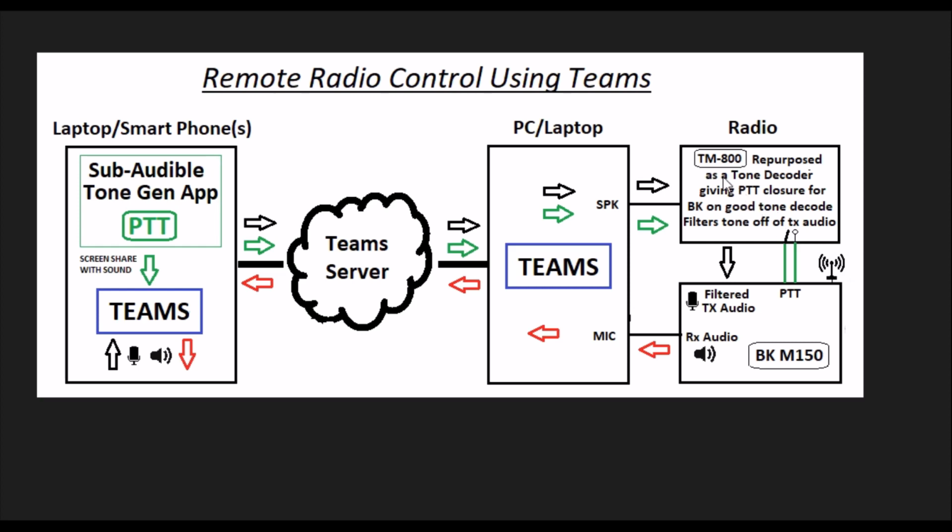But it works well. You do have to get the levels right, and all the other standard Teams settings that I talked about before, as far as no automatic gain control, any of that kind of stuff. Once you get the levels right, I did need to put in a 10K ohm resistor between the audio here and here, just because it's a high impedance mic input anyway.